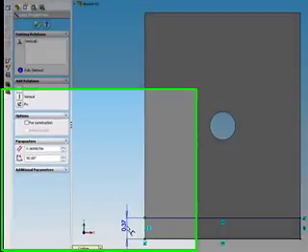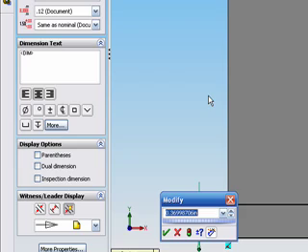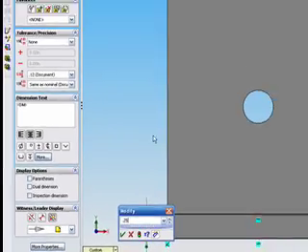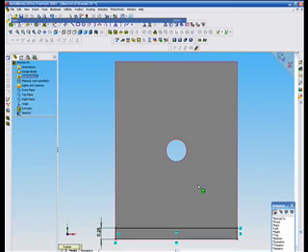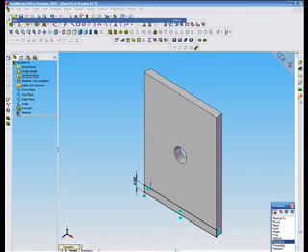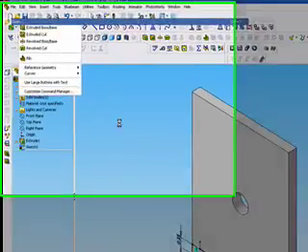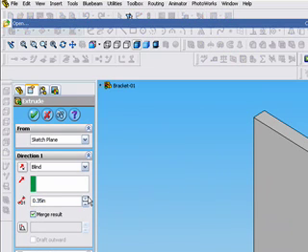Now we're going to go to the isometric, where you're going to be able to see this extrude. So we drew on that surface, and now we're going to give it an extrusion. As I use the up and down slider, you can see it go in, but for our purposes, I usually like to key in my dimension. So we're going to call this thing 3 inches. Now right here, by selecting merge result, which I believe is the default, you see it as a single part.